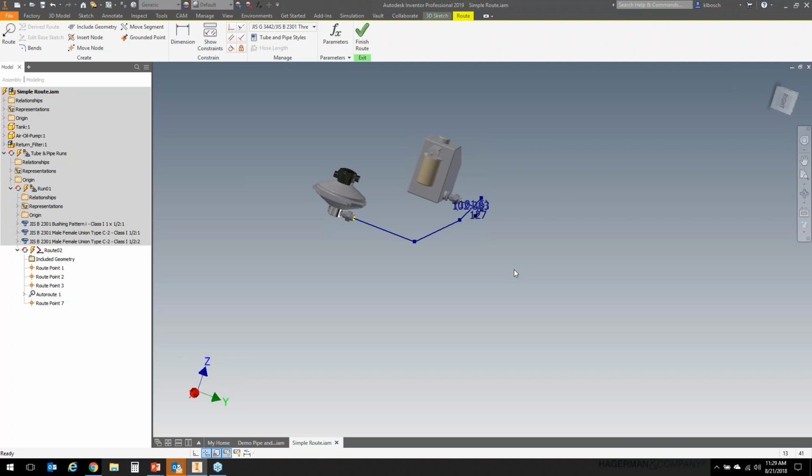And Anya, yes, if you've placed a rigid pipe and decide, you know what, I want to go to flexible tube, it does depend a little bit on how you started that. If your original fittings were of the rigid pipe type, then pretty much, yeah, you'd want to delete and start over because you have to have fittings for the flexible tube.